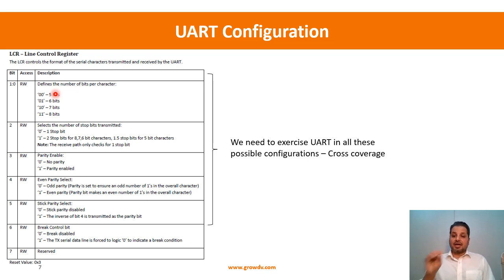We need to really be transmitting and receiving characters in order to validate the LCR. If I just program the LCR value and don't transmit or receive anything, it didn't take effect. Just programming is not sufficient. For control registers, you have to program different values and sample only when the corresponding event where it takes effect has happened.